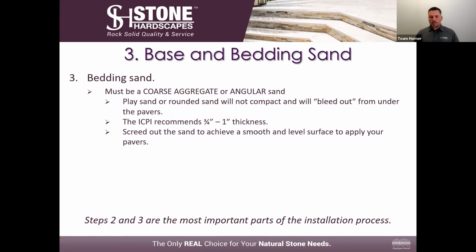The bedding sand is incredibly important. I cannot, as an installer, lay pavers, and should not lay pavers over the base itself. The base is going to give me a solid foundation, but it's not going to give me a level surface to lay the pavers down. The pavers will rock. The bedding sand will give me a nice cushioned layer for the pavers to sit on and help really lock those pavers in.